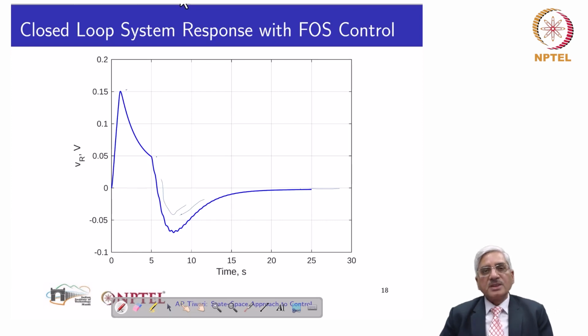And then this will be designed in the power range operation. Similar design has to be done for the system in the low power range and intermediate power range operation, and a kind of scheme to smoothly switch from the low power regime based controller to an intermediate range controller to a normal power range controller, that has to be built.